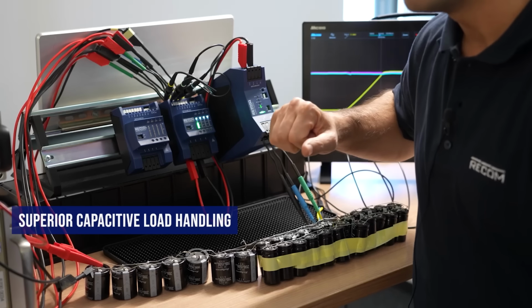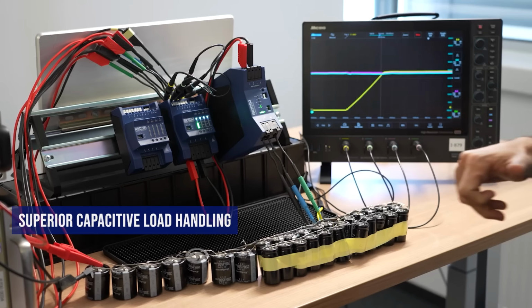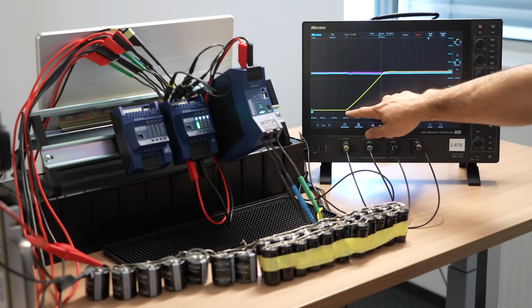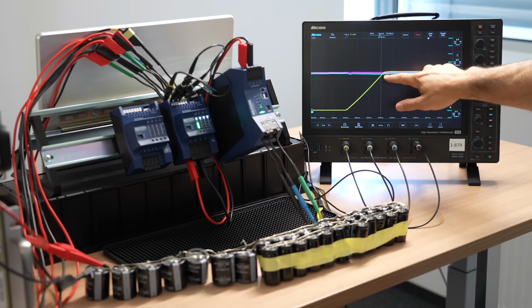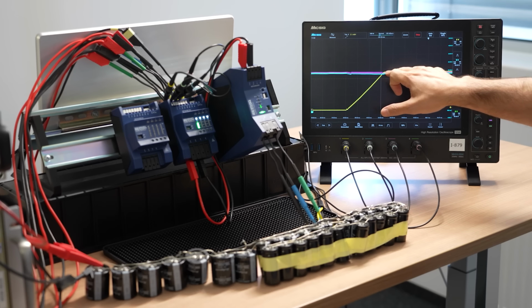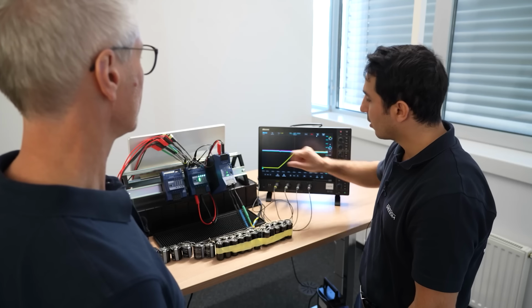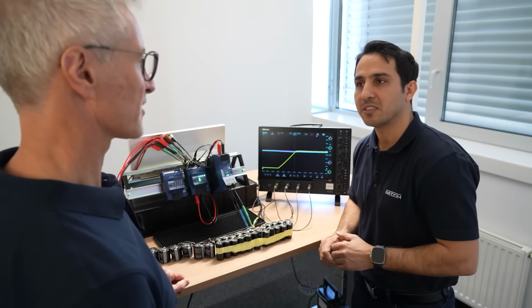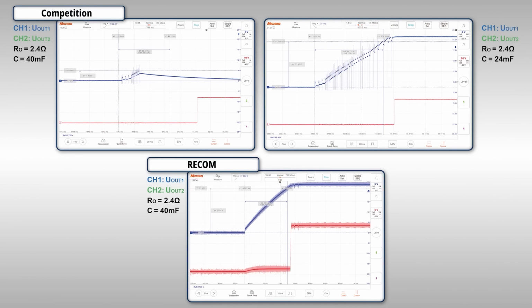Now we are enabling it, so it's fully charged. Now we see how it handled this huge capacitive load. You see here, very smooth ramp up and complete constant current mode, fully charged the load, and we see the other outputs are intact with zero effect. How do the competitors perform with their capacitive heavy load startup?